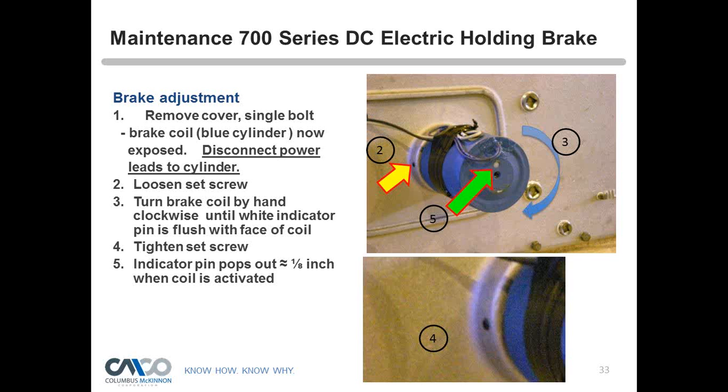And so how do you know when to further go into that hoist for evaluation? Well, one, obviously if you're seeing drifting and you've set the gap right, meaning that button is flush and it's working properly. But if you're seeing any drifting or anything like that, then obviously you would have to disassemble and get into the gear case to look at that brake. The other thing is if you're tightening it down and you can't get that flush anymore, that's a good sign the discs are worn, or you can't set it flush. So again, that would be reason to go in further to do that.